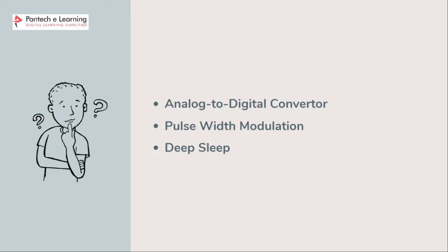In ESP8266 there are one or more ADC channels that can be used to measure analog signals. The resolution of the ADC in ESP8266 is 10 bits, which means that it can represent analog voltages as a number between 0 and 1023.